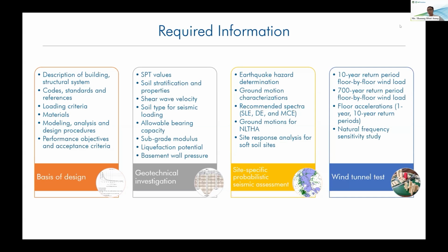For tall buildings, wind tunnel testing is also important. We have to engage the wind tunnel consultant to carry out the structural load study. For ultimate strength design, normally we use the 700-year return period wind load, and for the serviceability check, we use the 10-year return period wind load. The wind tunnel consultant will provide us the floor-by-floor wind loads for service level and ultimate strength design.